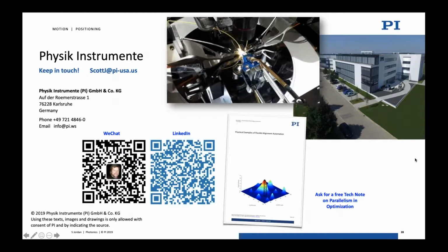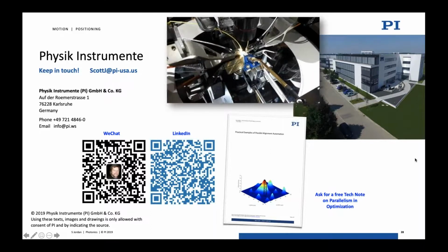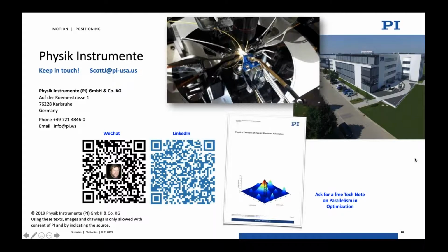It was a cell phone sensor made by Omnivision, I believe, and I was able to clock that at 260 frames per second and perform a 2D Fourier transform. I was doing all this in LabVIEW, of course, because that's my fate. And then that generated a figure of merit based on that calculation. So our system doesn't care. If you give it a hill-shaped function of some sort, it will find the peak of that hill. The only requirement is it needs to be fairly fast.